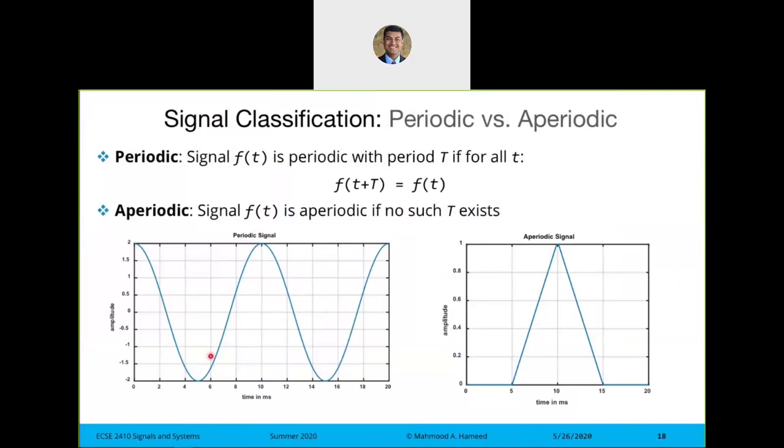A sinusoidal signal like this is periodic. But if it is periodic, mathematically, it has to satisfy this particular condition, which is if capital T is the time period of that particular signal. If it is periodic, then it'll have to have a time period. And if the time period of that signal is capital T, then the signal must satisfy this condition: f of small t, the independent time variable, plus the time period capital T should equal f of t itself. Let's check.